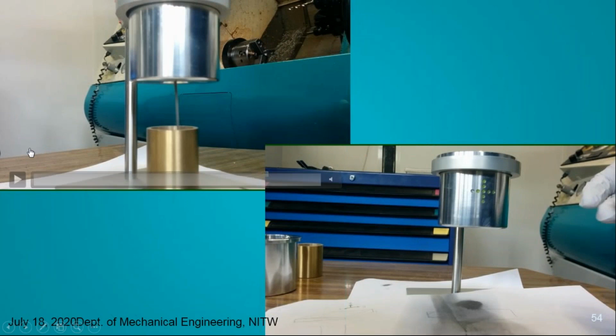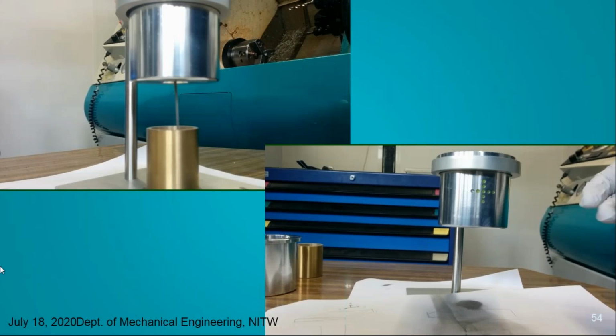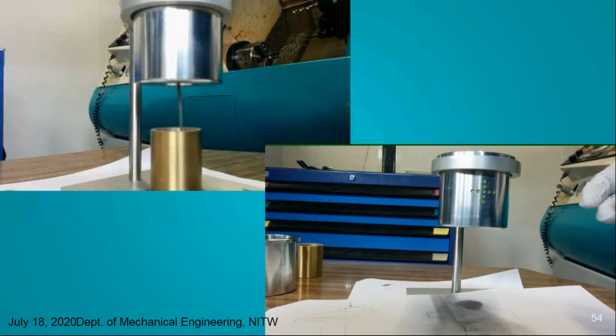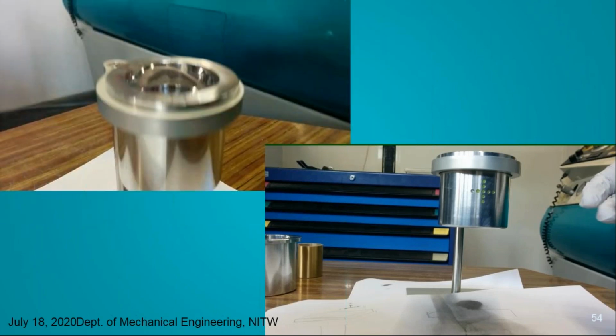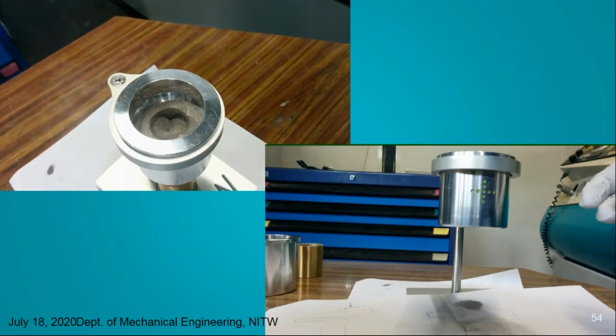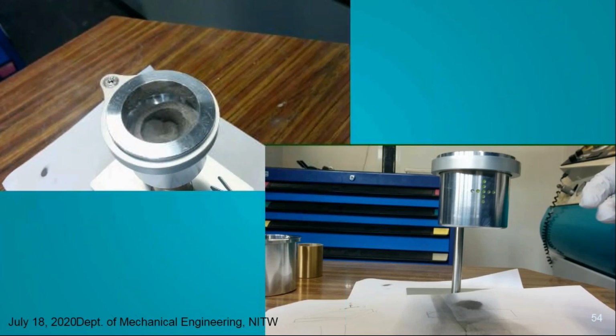You can see we have done the powder flow analysis with the help of a flowmeter based on ASTM standard B213. You can see here in the first video, the powder is continuously flowing, with no formation of arcs at all. Continuous flow of powder is happening, so the flowability is very good. Based on the time consumption, you can define how consistent the flowability of the powder is.